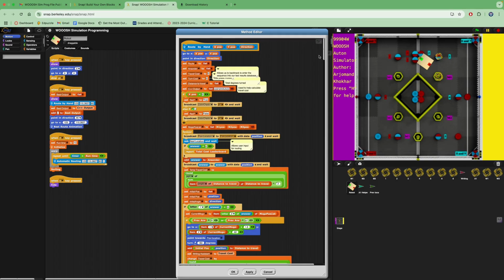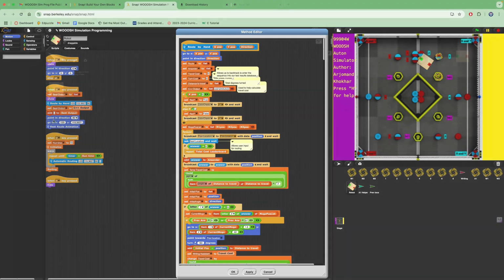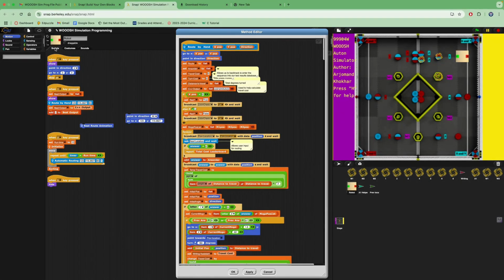So to start, if you want to use this block and you want to start in a different spot, this first parameter right here is going to be your X position. 123 for us is where the back of our robot is, right on that white line. That's starting as far forward as you can. In the route by hand block, it's going to be your Y position. So if you want to make this, say, 40, then it'll just move the robot down lower.